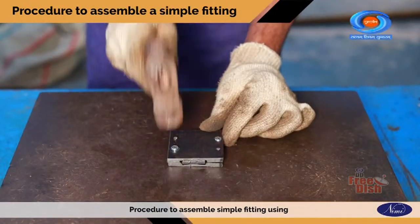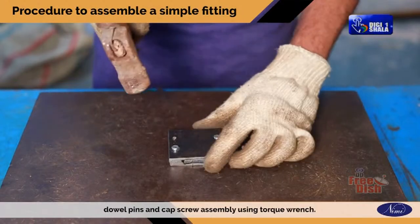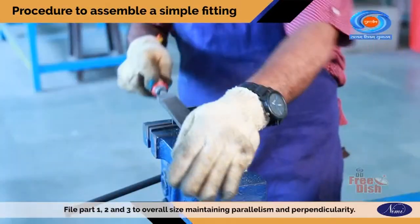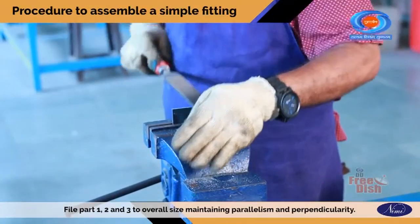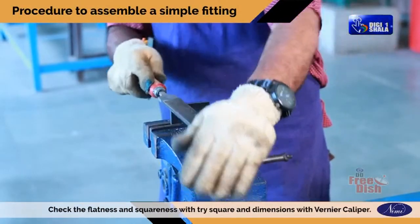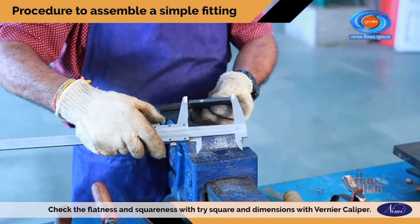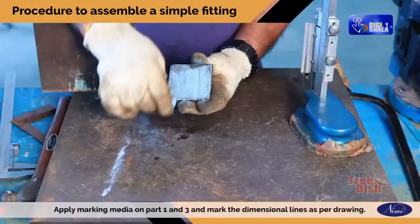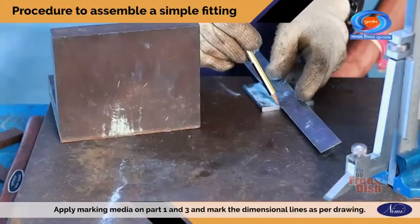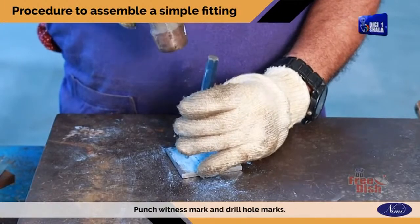Procedure to assemble fitting using dowel pins and cap screw assembly using torque wrench. Check the raw materials size. File part 1, 2 and 3 to overall size maintaining parallelism and perpendicularity. Check the flatness and squareness with tri-square and dimensions with vernier caliper. Apply marking media on part 1 and 3 and mark the dimensional lines as per drawing. Punch witness mark and drill hole marks.